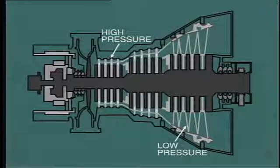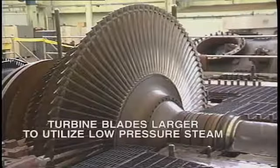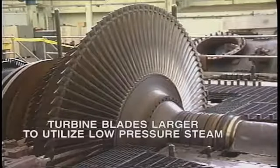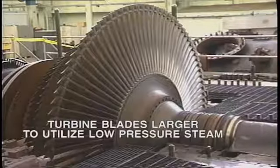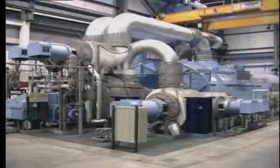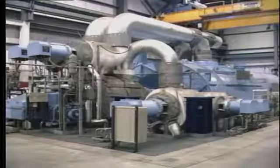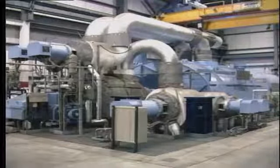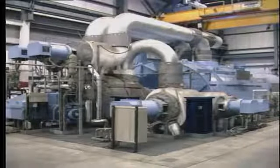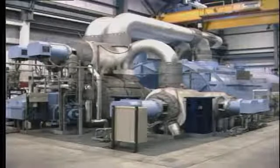This is very evident to the eye when we look at this single cylinder turbine. But notice, it is not only the casing that must be made bigger, but the turbine blades must also be larger in order to utilize this low pressure steam. On turbines of high output, say above 100 megawatts, it becomes physically difficult to make the cylinder large enough to accommodate all of the low pressure steam. To get over this problem, multi-cylinder arrangements are used, and let's look at some of these arrangements.